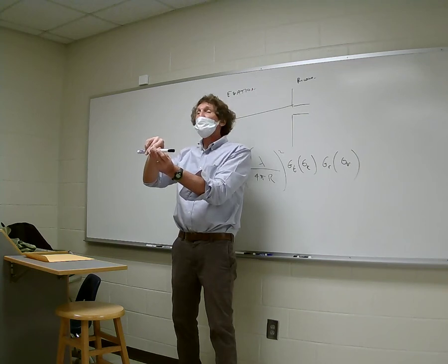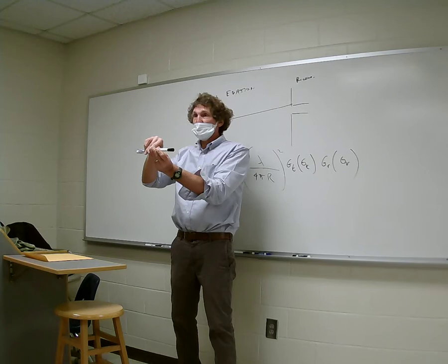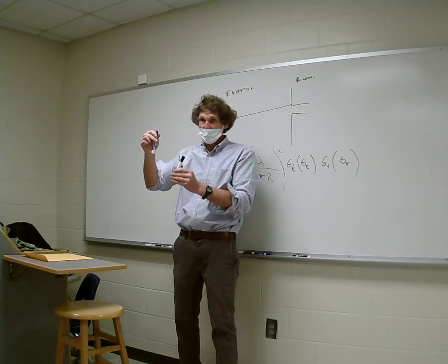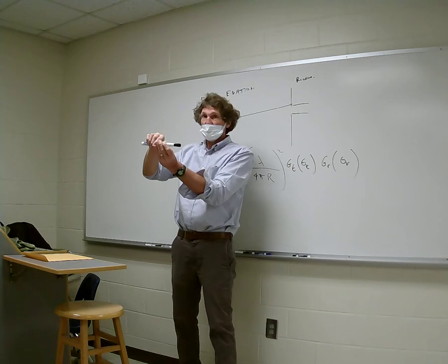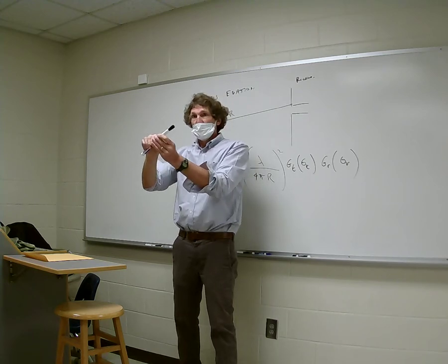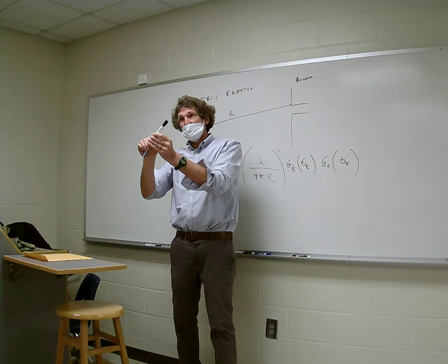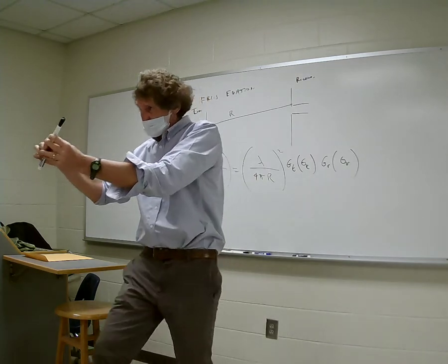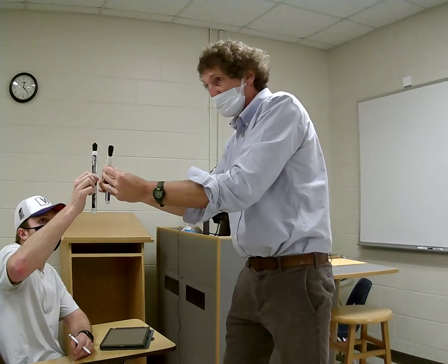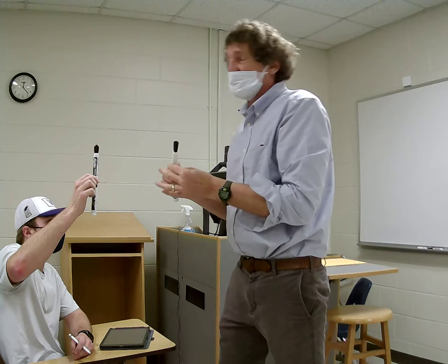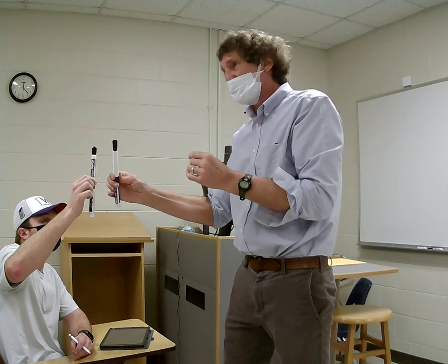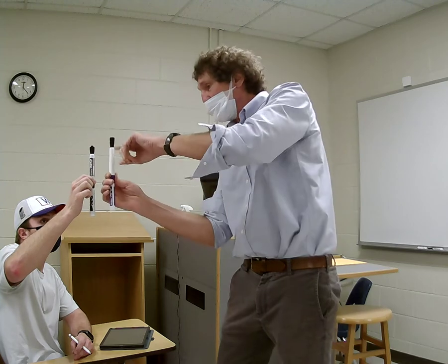Well, your gut feel is nothing's going to be received because the E field is polarized in this direction. You all see that? And your gut feel is right. If I cock it by 90 degrees, it's nothing. But if it's by 45, it'll be off by the cosine difference of the angle between this one, if I project it right onto the axis, and that one. You all see that, class? It's actually the sine of that angle. All right, cosine. Yeah, cosine of the angular difference.